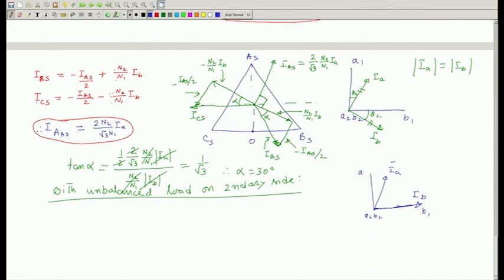The MMF balance equation will not change. The only thing is I will be deprived of this simplification, that the magnitude of I A is equal to the magnitude of I B. We crossed out that separate thing, no. So, its reflected current I A S, this I A you have to take in phase with this.